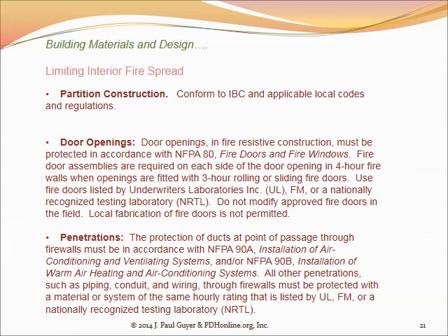And then the doors have a label on them that says this is a 1-hour fire-resistive door, or a 2-hour, or a 4-hour, or whatever. Same with window assemblies, usually with glass with windows. About the only thing you can do with the glass is to use wired glass, and that holds the glass barrier together for a longer period of time.